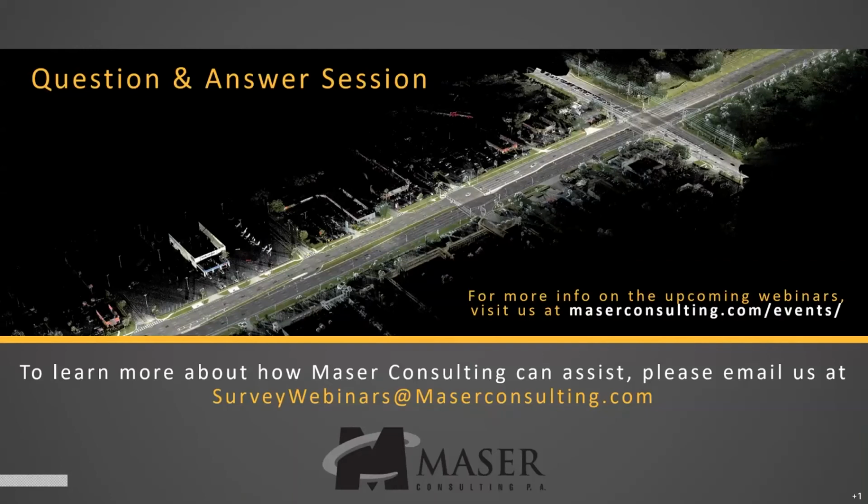And I think really that when you think about the accuracy, you have to look at the type of instrument, because I think the word LiDAR is used a lot. And it's kind of become a blanket statement for any type of point cloud, but not all LiDAR instruments are created equal. We believe we have one of the best in the industry, and we produce relative accuracies for this type of application of about 0.02 feet. It's very hard to verify to say, well, it's not quite 0.02 or it's 0.01 or it's 0.03, but very, very accurate results.